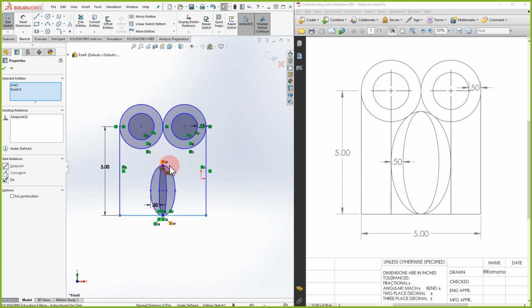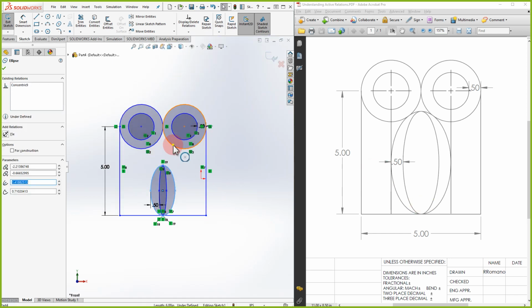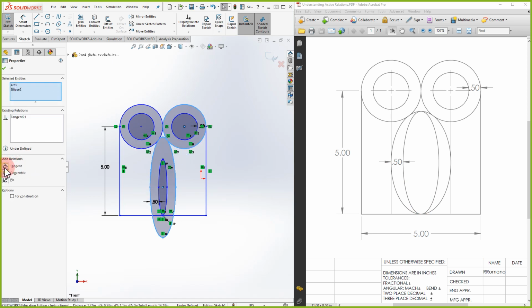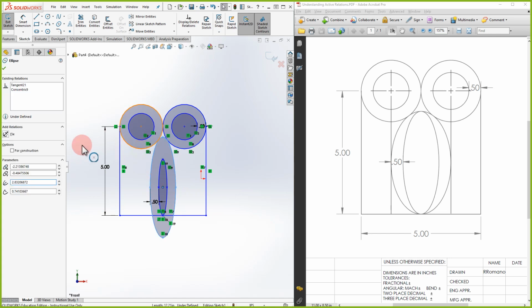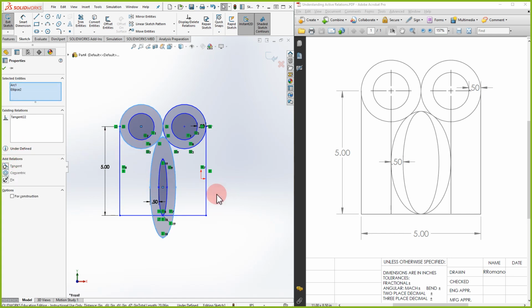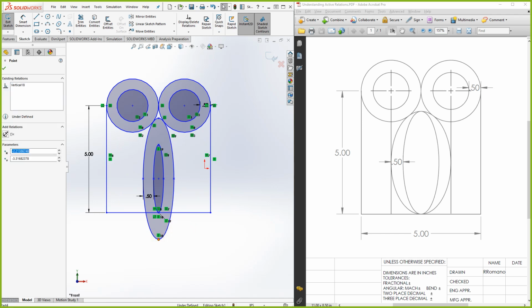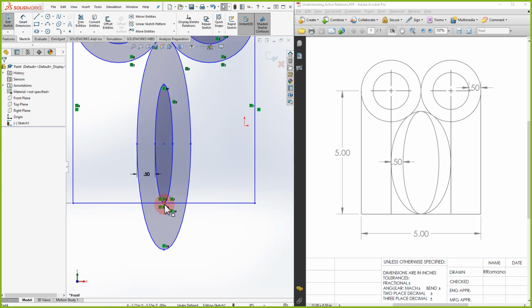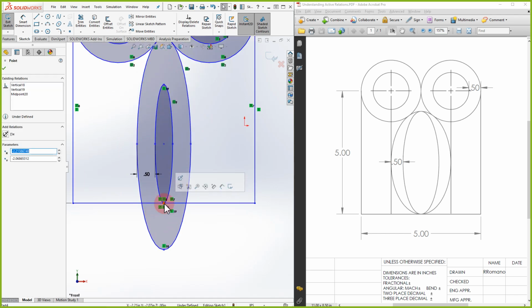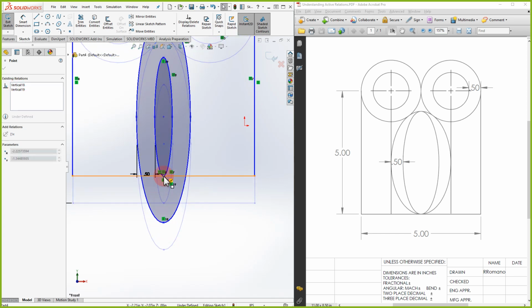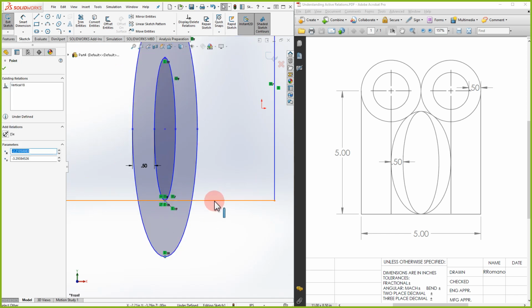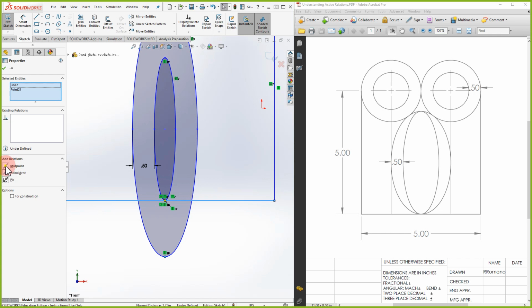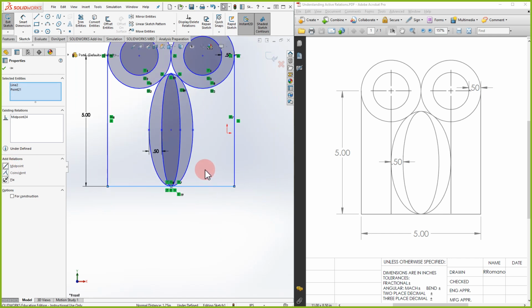Now what we have to do is make sure our outer one and our circle become tangent. There we go. We make sure this one here and this one here are tangent. And I think as well, make sure this one here, oh, I grabbed the wrong point before, it looks like. This one here should be, get rid of midpoint. Oops, I have to constrain that afterwards. This one here and this line here should be stuck to midpoint. There we go. We're getting the shape now.